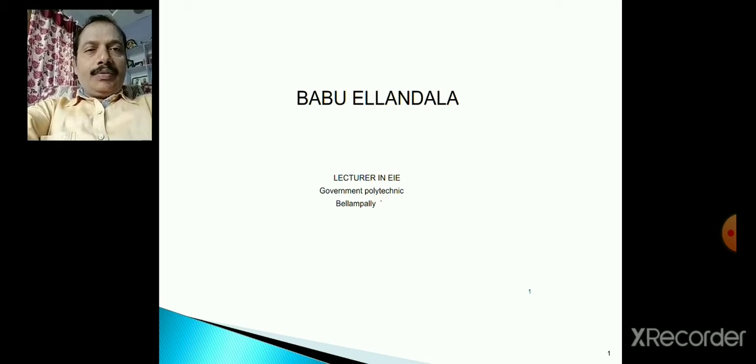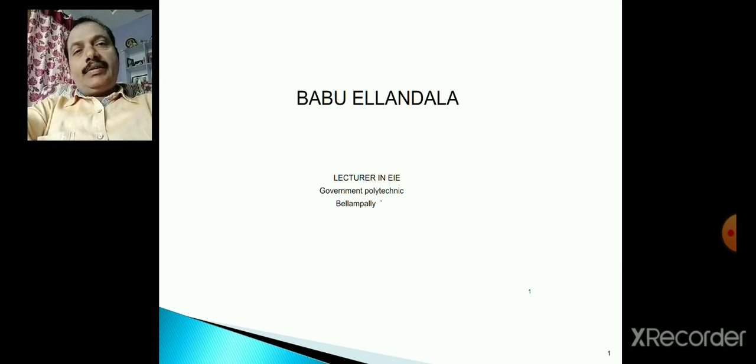So in the asynchronous counters, we have discussed the decade counter also, the counter which will count from 0 to 9. And after that we have discussed synchronous counters. In the synchronous counters, the clock signal is applied simultaneously to all the flip-flops. So that is the synchronous counter. In this, we have to follow certain procedural steps to design the synchronous counter by utilizing excitation tables. Because you do not have such a requirement in your syllabus, we are skipping that procedure, and directly we have written input design equations for the counter.